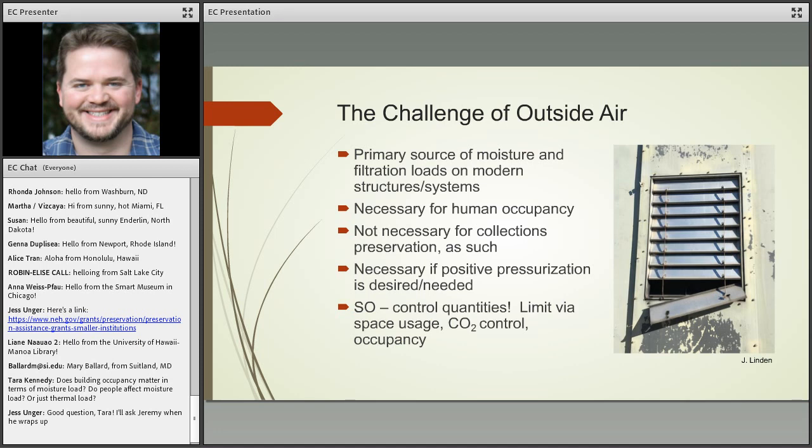This has been a past consideration, something that was regularly recommended in terms of building and especially environmental design. That is actually regularly changing. The more that we think about it today, there's a lot of movement out there, and some of the guidelines have changed or will be changing soon that are calling less for positive pressurization as the understanding going in, and really thinking about it in terms of a more neutral pressurization to the positive side, which is to say that we don't want to bring in so much outside air just to positively pressurize.